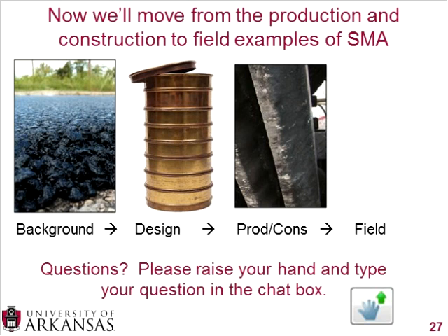And if you only have 3 coarse aggregates stacked up, there is a possibility that if there's something wrong with one of those, then you've lost 33% of your structure. Whereas if you have 4 coarse aggregates stacked up, and there's a problem with one of those, then it's possible that you might not have as many long-term problems. So be a little more conservative with your pavement thickness, recognizing that the coarse aggregates are much more critical, that would be my guess. So thank you for that question.